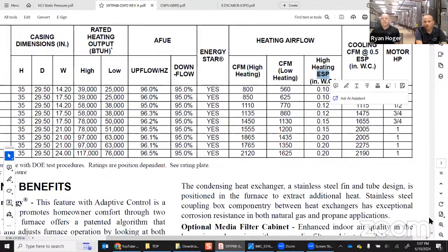The filter, the evaporator coil, that affects it, yes. But when we're talking about that static, just remember that it's that immediate piece of equipment we're talking about, like the furnace. We don't care about the extenuating stuff, all the stuff hanging on the outside that we figure out is maybe what's helping the static be bad or poor, however we want to look at it.